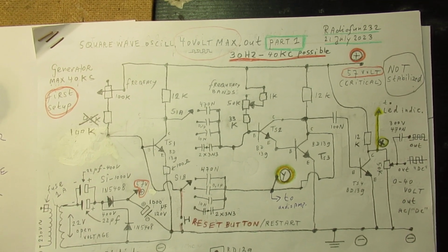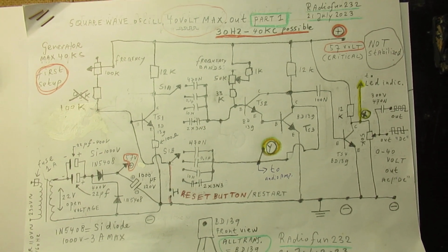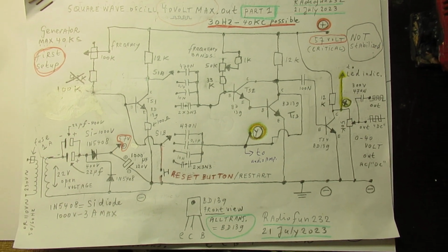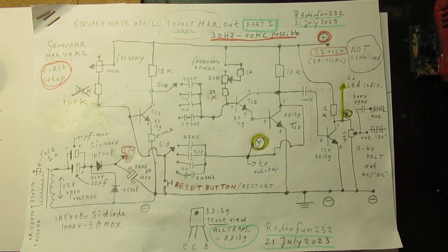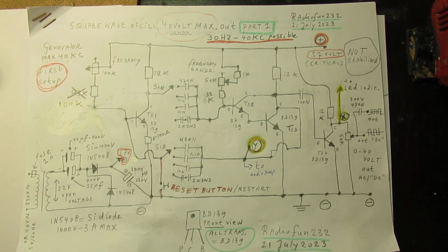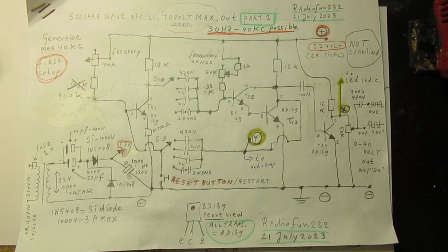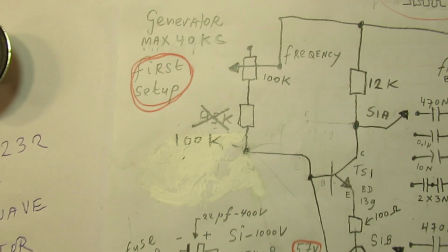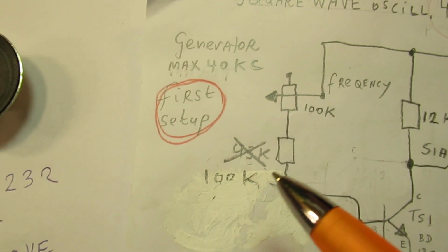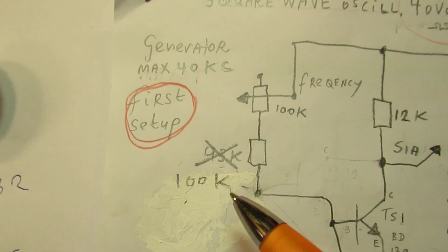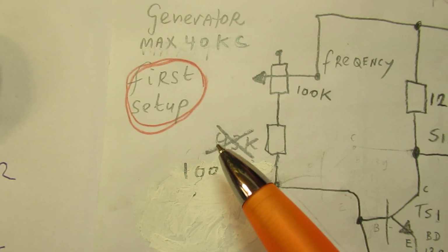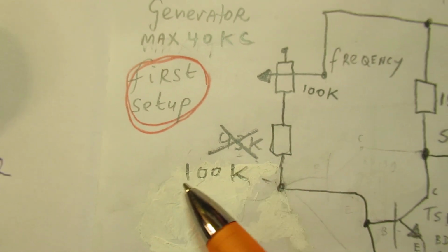and this is that original schematic. I have changed the value of one resistor. Only that one gave better properties. Changing the value of that one resistor has given better properties, especially about the restarting of the oscillator. So it was in the earlier schematic 43K, now it is 100K.